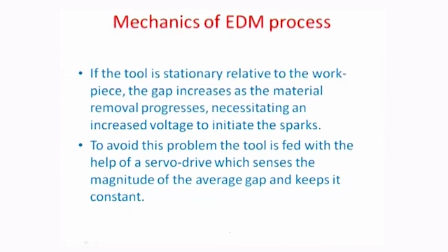So now a situation has been obtained where there is an electric field, there is a potential, and slowly the field is growing so that it exceeds the breakdown field of the medium. If the tool is stationary relative to the workpiece, the gap would increase as the material removal progresses. For an obvious reason: there would be melting wherever the spark is generated, and because of that there is going to be an erosion. The melt is going to come back into the dielectric fluid, and one of the surfaces, in this case the workpiece surface, recedes away from the tool, thus creating more distance and a situation where the electric field would no longer be equal to the breakdown field, and the spark, or a set of sparks, would simply cease to exist.